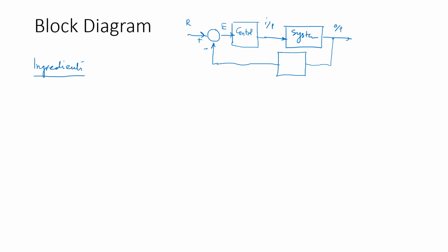So one ingredient that you can see is what we call the summing junction. And this is this round block. You can see that the signal gets in there and also gets in there, and it produces an output signal. So this is going to be summing these two signals up. If this is A in the frequency domain, for example, and if it is B in the frequency domain, you can have this to be A of S